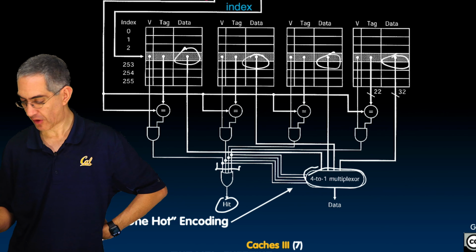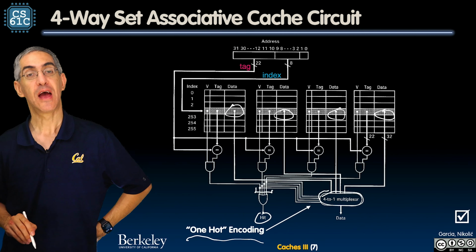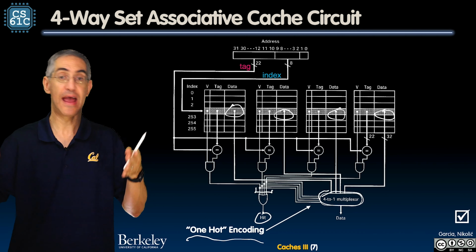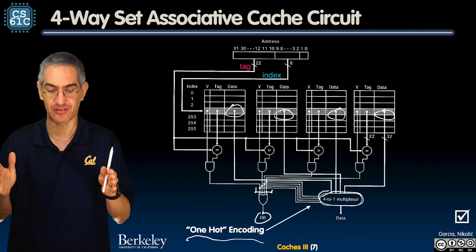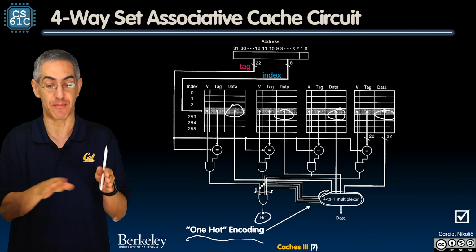And those 4 signals, let me zoom back fully, we're going to call one-hot. And one-hot is exactly as you might imagine. It's a set of n lines in which I promise you the spec is, on this one-hot system, only one of those will ever be 1 at a time. They'll all be zeros by default. And when you want to drive the second one, then this would go high, but everyone else would go quiet. So only one is ever hot, or 1, ever.